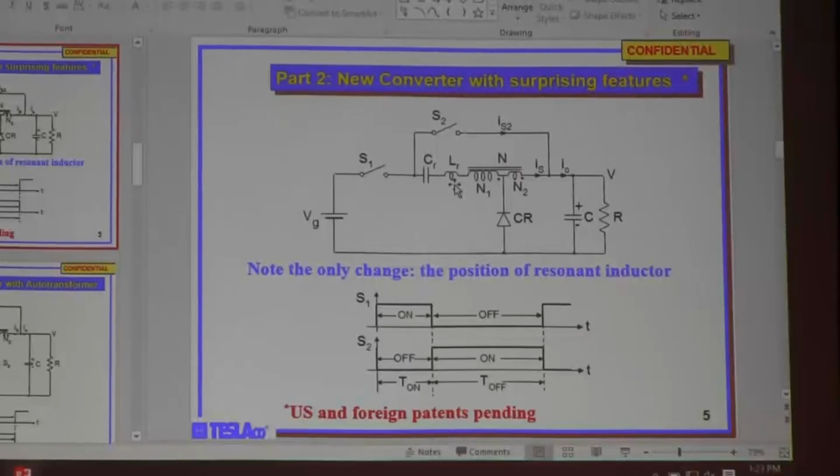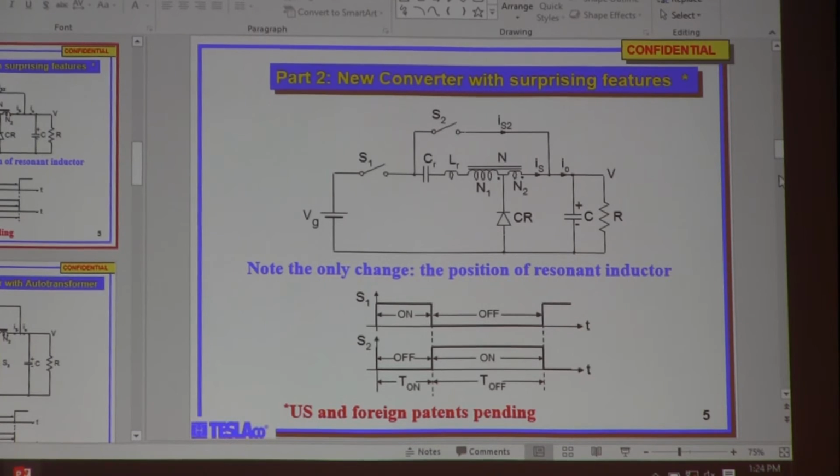That transformer, the Faraday kind, works a little bit differently than Faraday's because it's not excited. It's excited by that AC current, and it's a current transformer. So whatever is the current on the primary, with a 10 to 1 turns ratio, the ripple current on the secondary is 10 times increased. And what happens? It's a summation of the step current of the tapped inductor and the continuous AC current of the transformer. When they add together, they eliminate the jump on the primary and the jump on the secondary, and the magic works. Okay? So that is basically my conclusion.